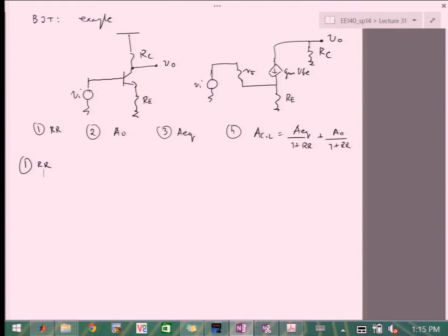Now, in the book, there is a little bit of a difference between that and what I just said, in a sense that they say you have to locate the dependent or controlled source, which would be this, and then replace that with an independent source, and then also monitor the variable that controls this one. That will be a return ratio, right?